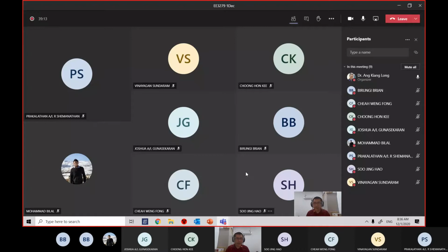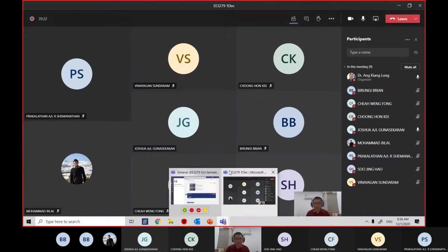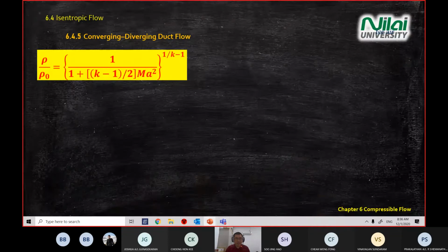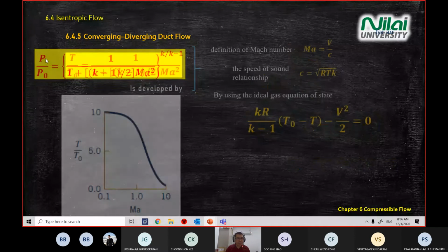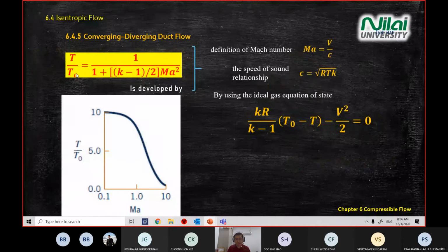The next one I'm going to ask is Vina. Vina, stand by for the answer if Joshua is not able to answer. To find out the Mach number, sir. In what scenario? Is it all these three equations? Rho over rho 0 with the stagnation, P over P0, and T over T0. So in what kind of case are we going to use these three equations? Do we use this one in the incompressible scenario or the compressible scenario?